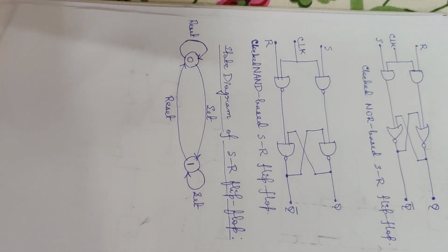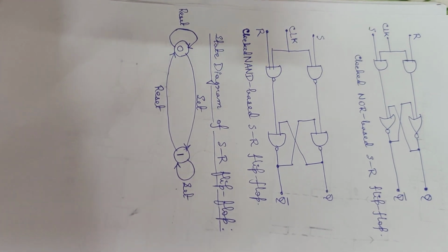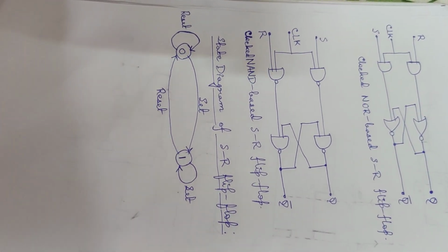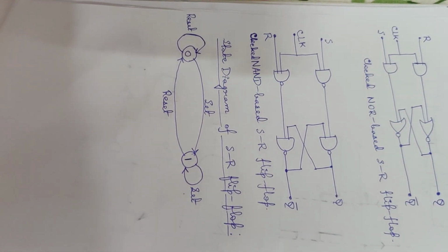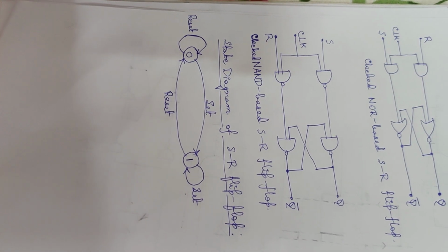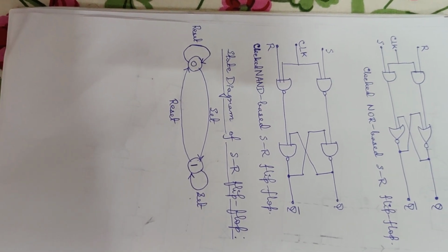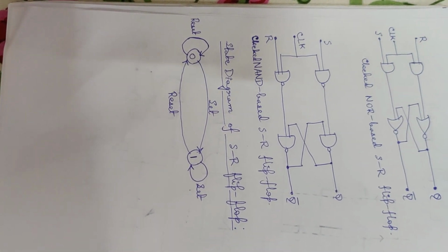Hello everyone, today I am going to discuss SR flip-flop. I have already discussed gated latch. So what is the difference between a gated latch and a flip-flop? A gated latch uses enable input and a flip-flop uses clock input. The function of clock input is the same as that of enable input.